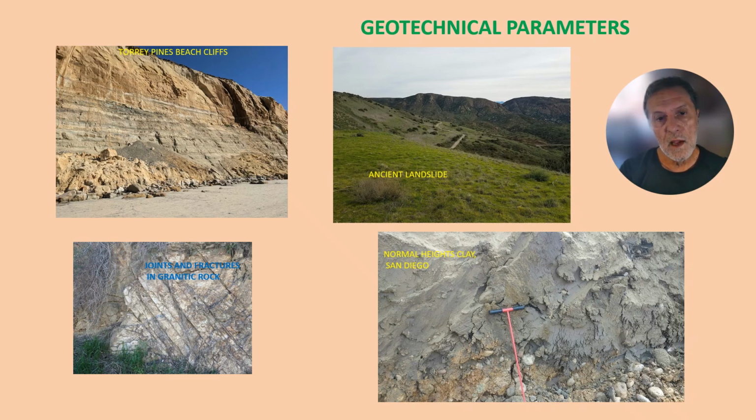And lower right, we have what's called Normal Heights clay, Pleistocene age clay, claystone, very stiff, very expansive, very plastic. By expansive meaning, if you add water to this material, it will swell. Presents, again, a different sort of problem to the engineering geologist, whether you want to go through it with deep foundations or remove it and replace it with something else, or perhaps mix it with a lime mix that might strengthen it.